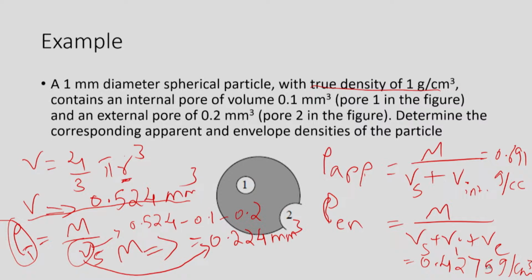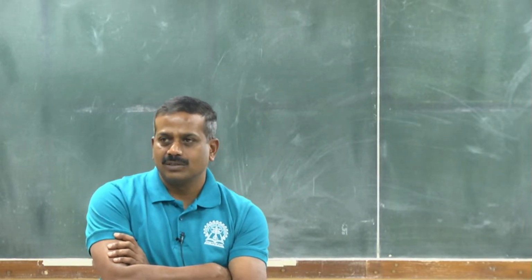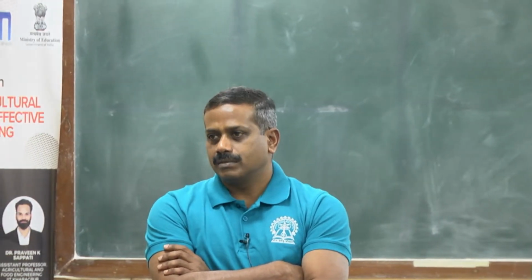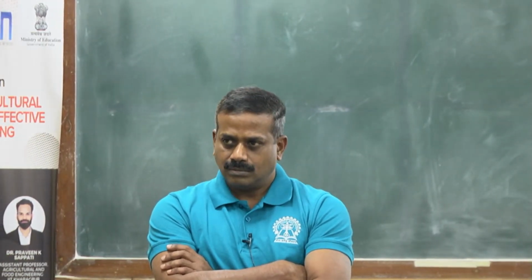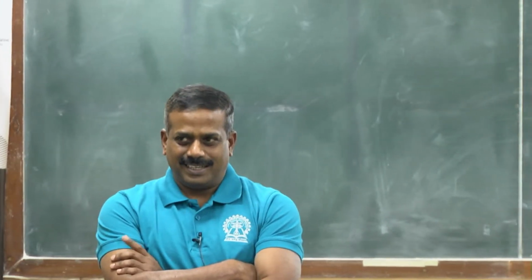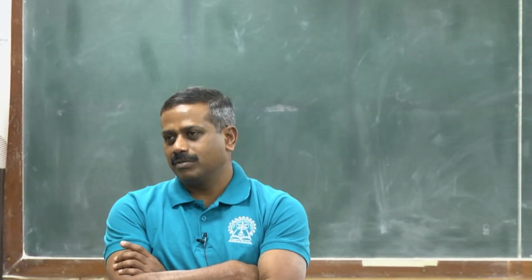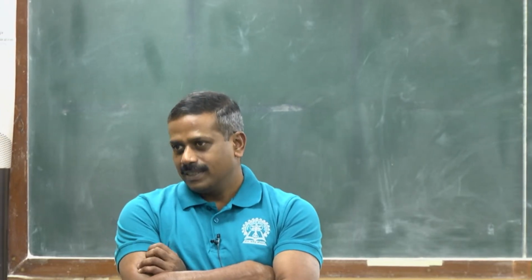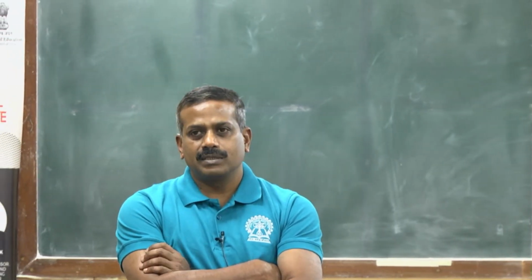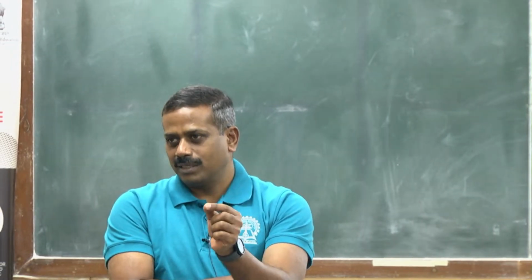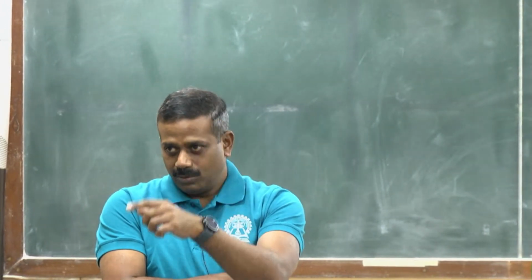So envelope density again, it's for individual particle, right? So it will be very difficult to get the gas. There could be some multi-layer adsorption, right? Talking about density, it's only about every particle or unit volume. Here we are talking about particle density, but we are not measuring for a single particle. If the particles are smaller in size, we use bulk powder to quantify single particle density. So we'll talk about that.